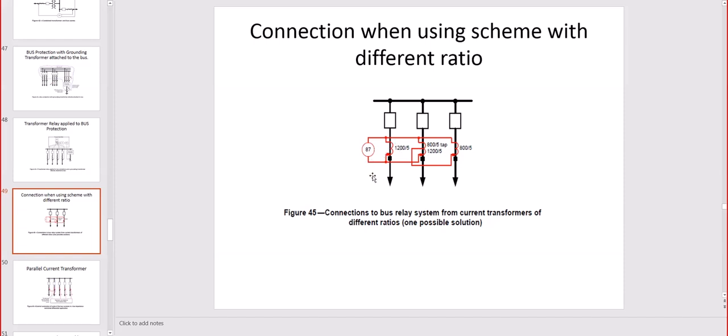In the new relays, that is absolutely no problem, because you will set up the inputs to the 87 function in a digital relay. It will know, because you put the right setting, what is the ratio and what is expected as an output as normal secondary current.